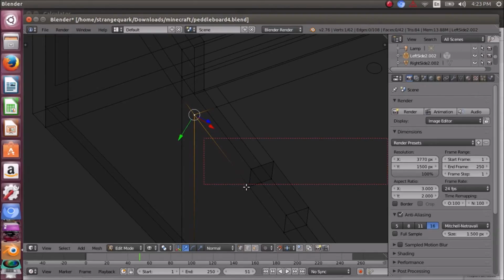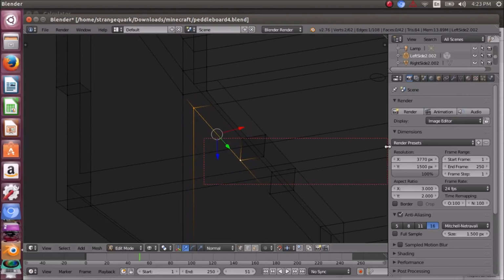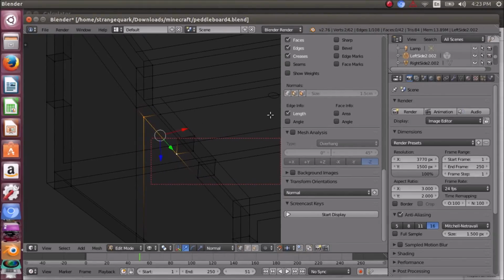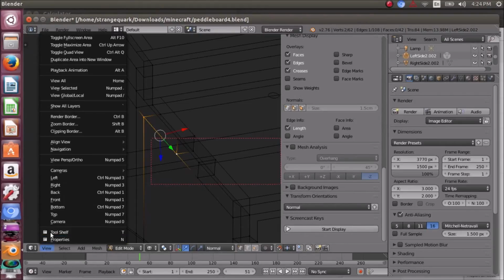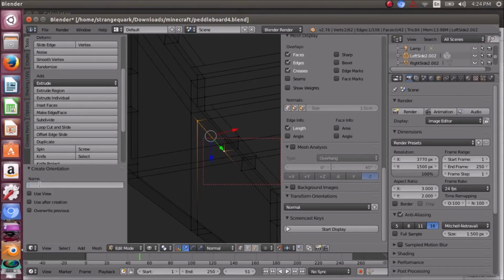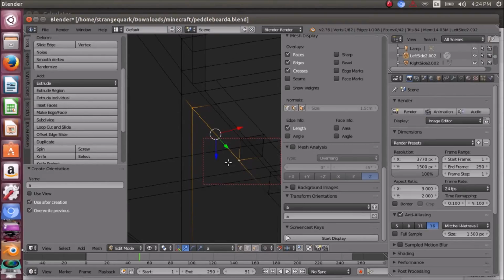To record that, you can select two vertices that are matched up to the edge, and once we match that, we can go down to the transform orientation, hit the plus key, pull up our tools shelf real quick, and in this dialog I type in A. As you may remember from the previous tutorial, we record the transform orientation, and lo and behold, it is recorded.